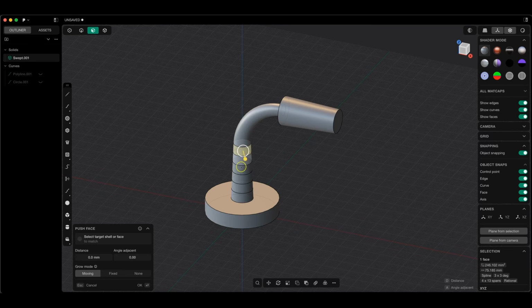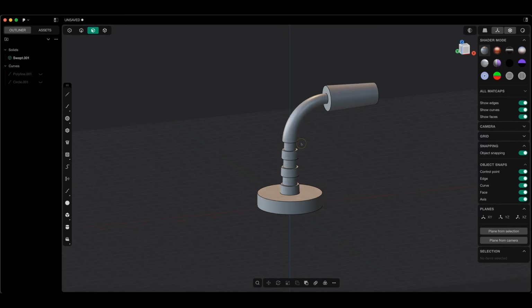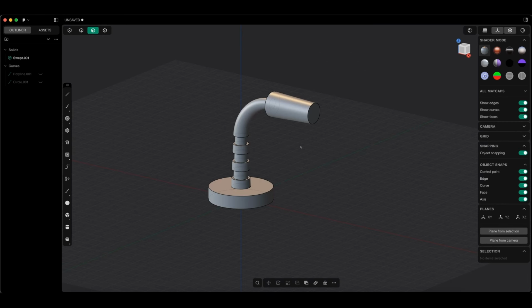And now, for example, I can select these surfaces with the Shift key. I can gently drag this marker, click OK, and the changes are applied to the model. We'll finish this example here. Here, I mainly wanted to show you the sweep operation so you can create a solid by extruding a profile